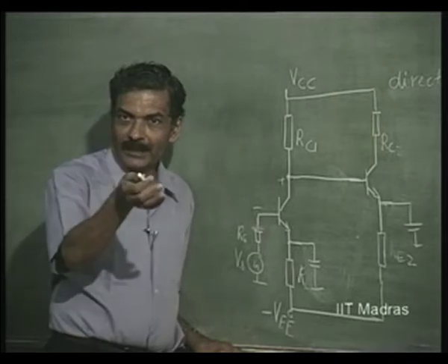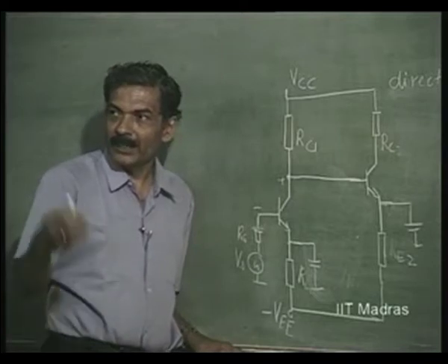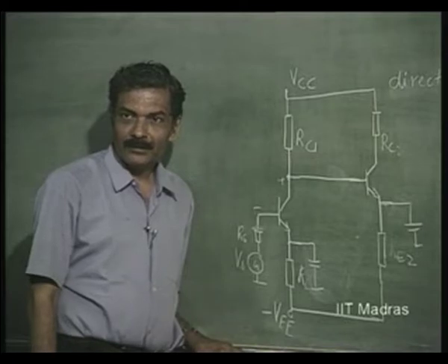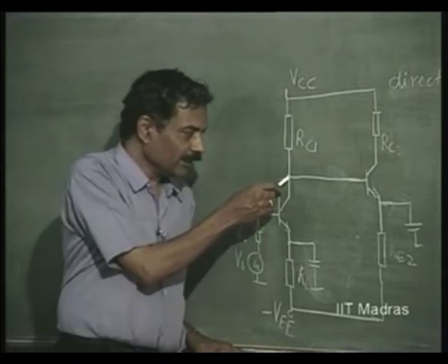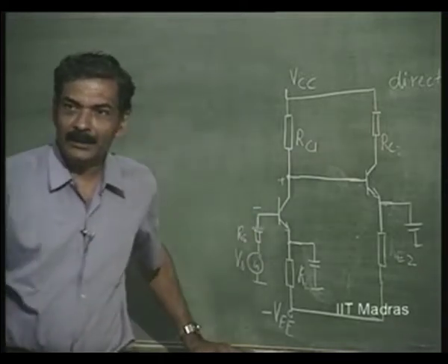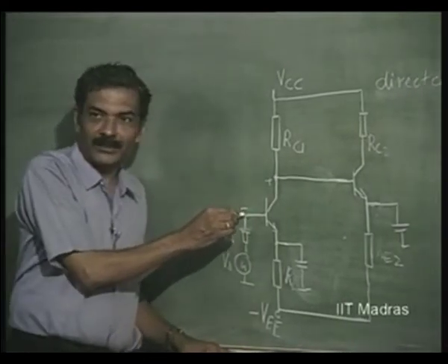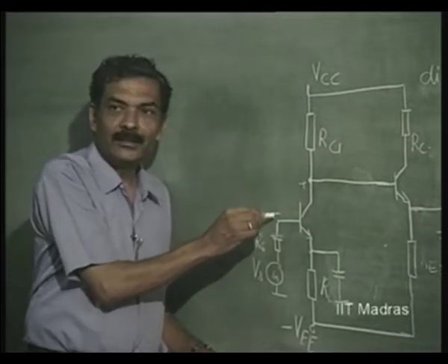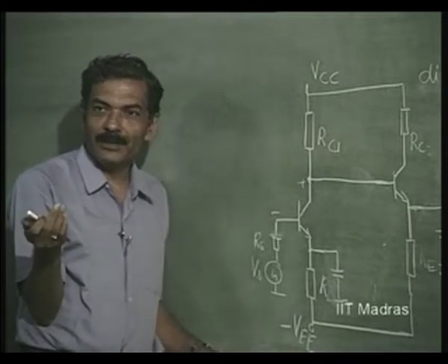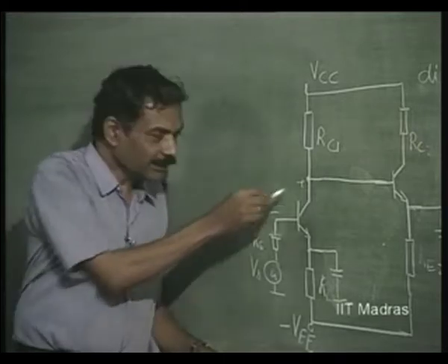So, output stage is handling 10 volts. Okay. So, this output of the first stage is handling only 10 volts by 100. Okay. So, this is an important aspect. That means, the voltage swing needed for the pre-amplifier is normally extremely small. So, you do not have to provide, actually speaking, any VCB at all, or even if you provide it, a voltage of the order of few volts or hundreds of millivolts is sufficient.